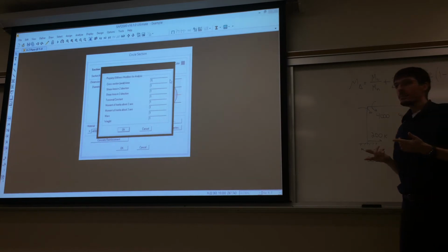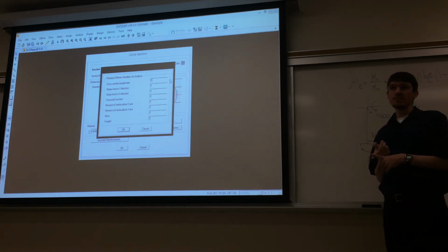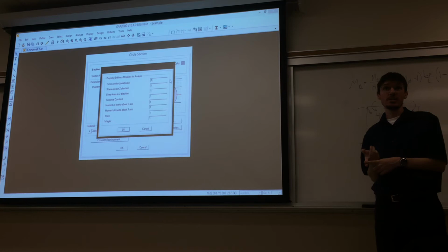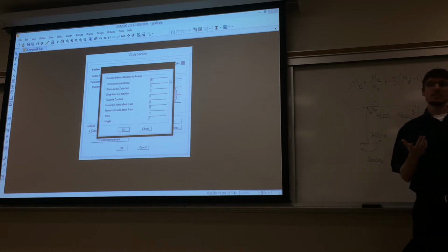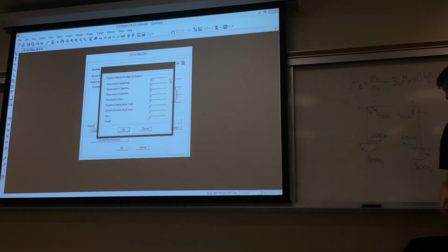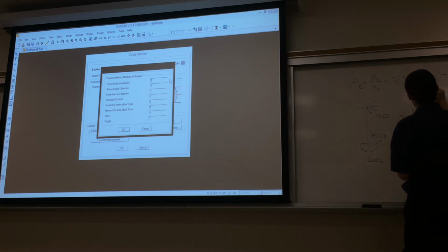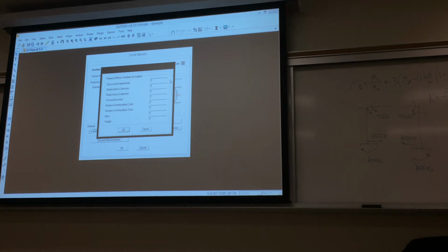What does that mean? It means you have a member which is essentially axially rigid, which means it's incredibly stiff. How does stiffness contribute axially to members? Well, your axial stiffness is AE over L. So how would you increase the stiffness of these members?